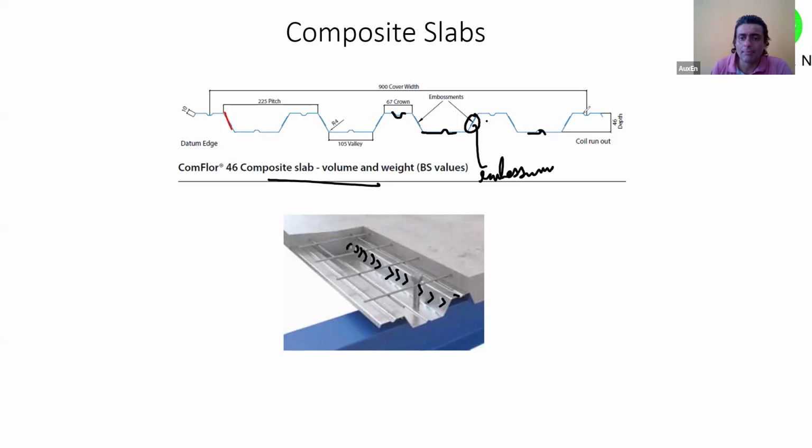This will act as a rib. This will also act as a rib. It helps you to prevent the local buckling of these thin plates. These things we will discuss later; we are just introducing different topics to you. So these are the dimples or ribs, running along the length. I don't know if you're able to make out, but this is a rib that is running along.